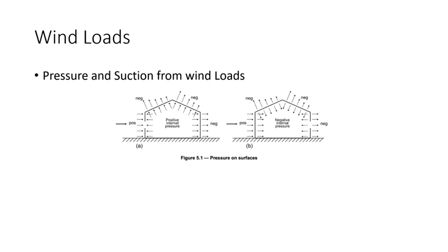When wind load is considered, we have Indian codes and American codes, which have a special explanation for these loads. One is an empirical way of applying the wind load on any structure. And some structures, like very high rise structures such as Burj Khalifa and some other structures which are almost 1 kilometer from the ground level, have a huge wind impact. For those structures you have to do dynamic analysis, where you will study the drift due to the wind.